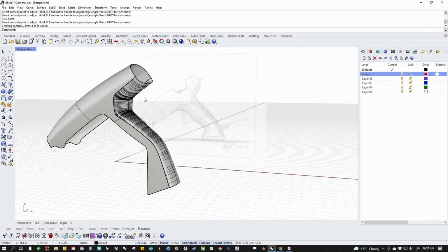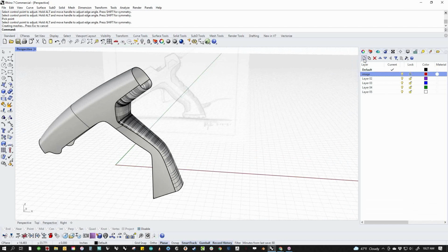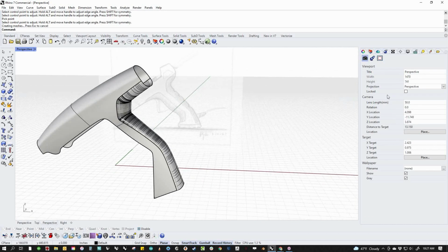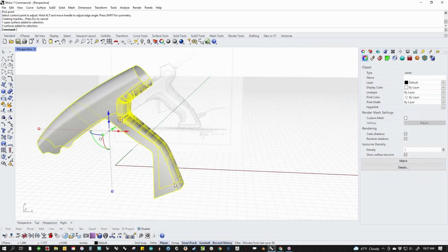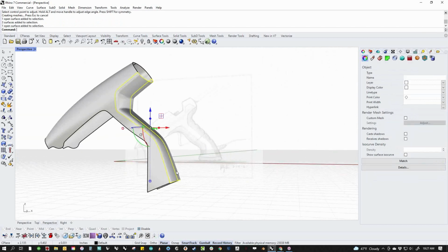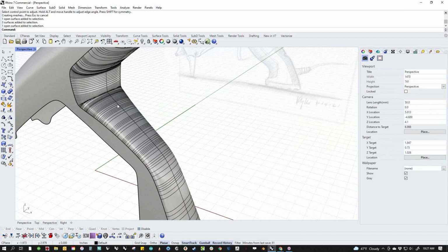We could mess with this. Now this is a horrifically ugly surface and we probably don't want to do that, but you could essentially just blend that, and then if you really wanted to lie, cheat, or steal, shut your properties off here, shut off your ISO curves and, whee, now it looks great, right? You can hide a lot of lies. You can hide a lot of horror by just shutting off the surface ISO curves if you wanna make yourself look fantastic. But this is probably not great.